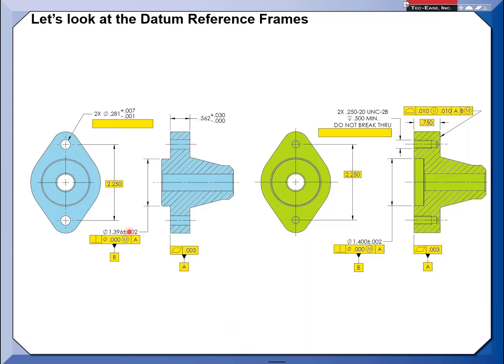So now, with that being said, that kind of sets us up for the story, and there are some things I want to talk about first, and it's a little bit more than this challenge. These are the things engineering has to do. In this case, they had a flatness requirement here, and they came up with 3,000ths, using a rule of thumb: how flat do you keep a surface? You notice the length of this flange is approximately 3 inches, maybe a little bit more. So what they wound up doing is basing the flatness on about 1,000th per inch. So over this length, they picked the producibility of 3,000ths flatness.